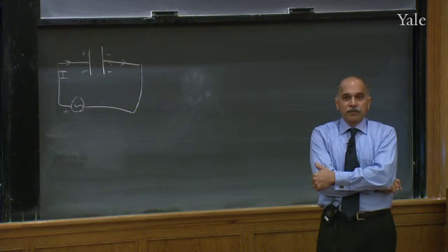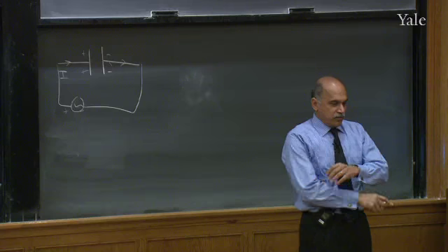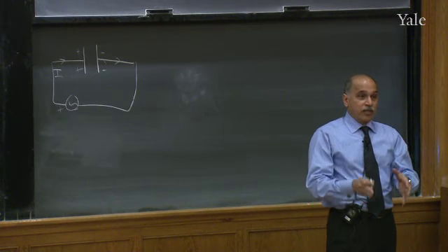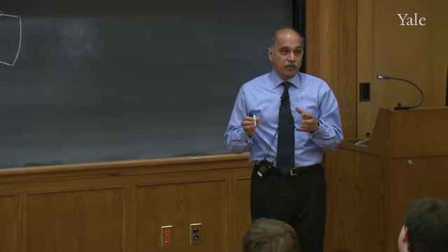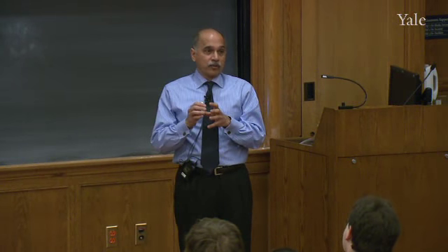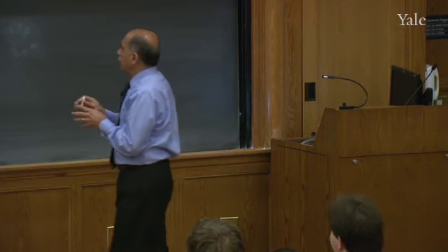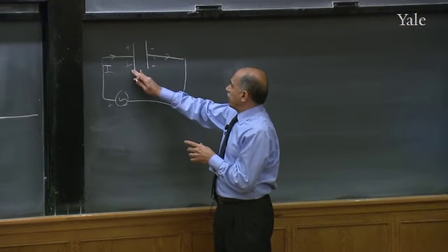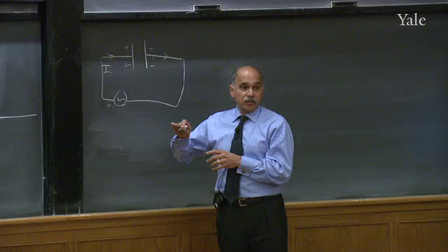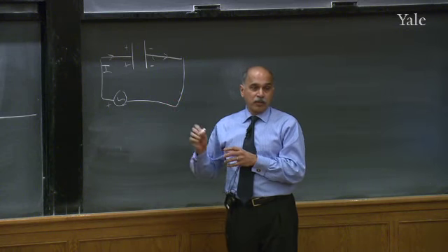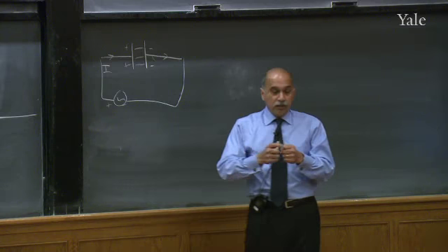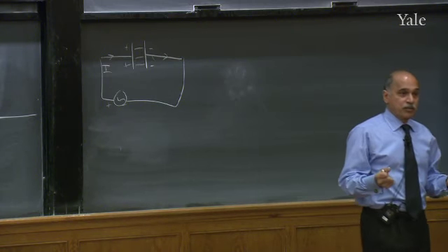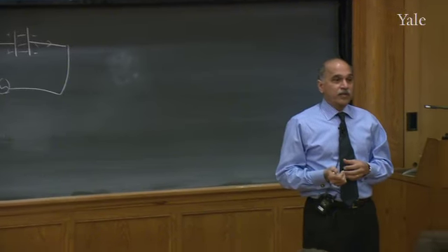It'll jump the gap if here's what happens. Depends on what's in the medium. If you put air, for example, the air molecules are all neutral. So there is no way for the plus charges to ride them and go to the minus terminal. But if the electric fields, and this will certainly produce electric field, are so strong that you rip out the plus and minus charges, then suddenly you've got a bunch of free carriers.